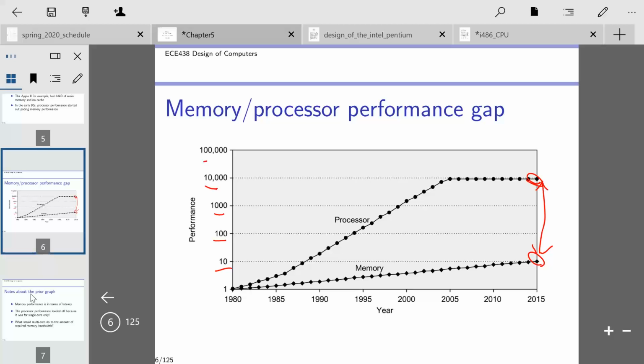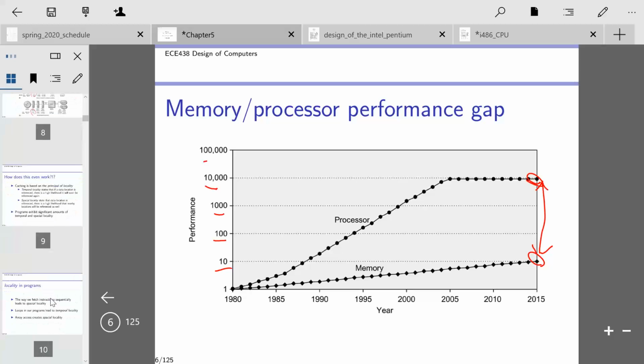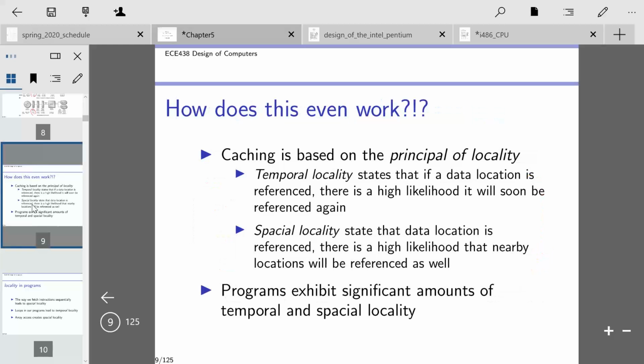For example, in terms of DRAM, we just increase the number of DRAM chips that we access in parallel and increase the amount of wires between our DIMM, dual inline module, and our processor. Now, of course, I say we just do that, but I/O pins are a precious resource, so we can't always do that easily. But also with the DRAM, we pipeline it, right? So pipelining allows us to improve the bandwidth. And so again, we want our memory hierarchy to take advantage of that bandwidth that we have at the next level.